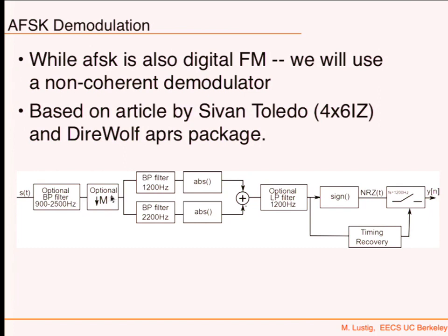Okay. So then it goes through matched filtering. Now, what's matched filtering? We know that we transmitted a pure frequency for a particular bit length. So what we're going to do is convolve it with a frequency at that length. You could just do it with a rect window at exactly the same width, but what we're going to do is a time-bandwidth product of 2, so extend it to 2-bit length, but then window it.